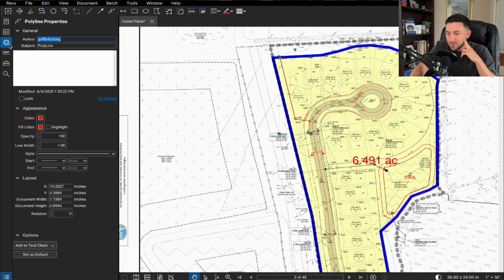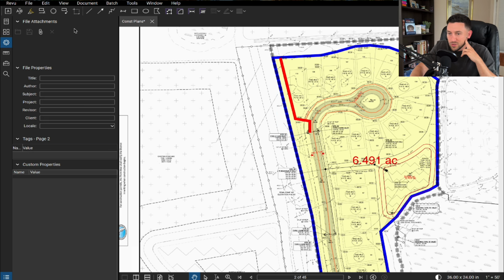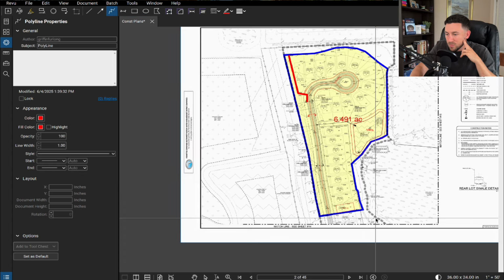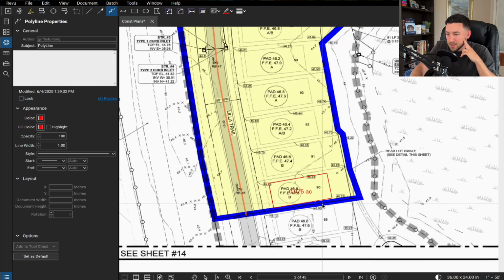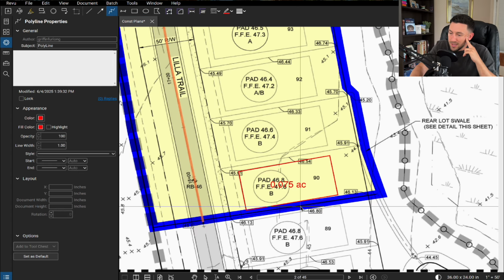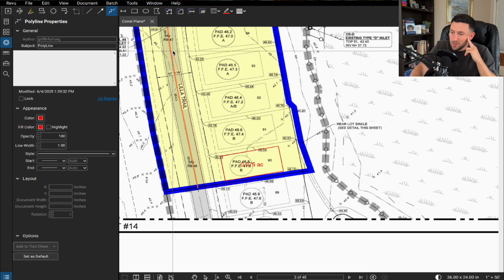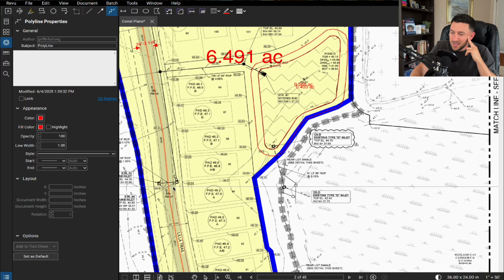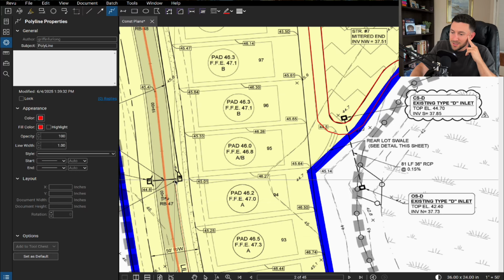Let me fatten that up just so you guys can see it. So that's a water droplet there. And guys, you don't have to be absolutely perfect, but it has to make sense. So here's a high point here. That's a low point. So high point here, it goes into the road, travels along the gutter line, and then finally into this curb inlet system.